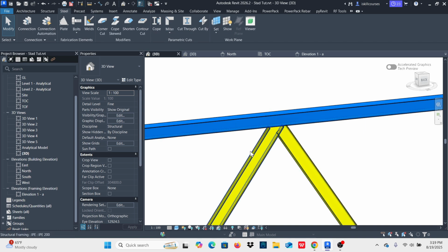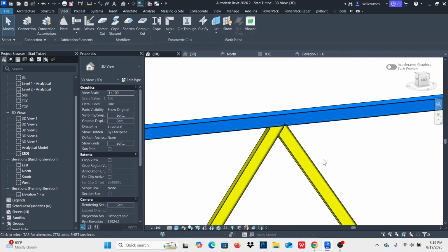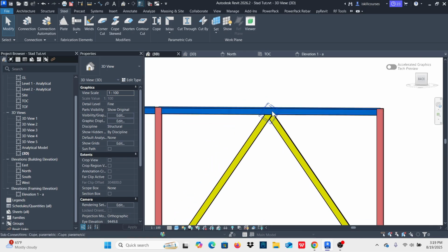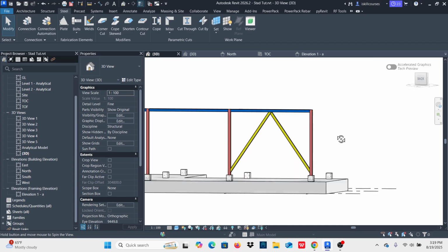Okay, now I'll copy this against this one. I'll select this member. Actually, copying is fine. I'll select this member, hold Control, select this one, right click and finish. Okay, now my joint is okay. So the copying means that I'm just welding on those points, so it's okay the way it is.